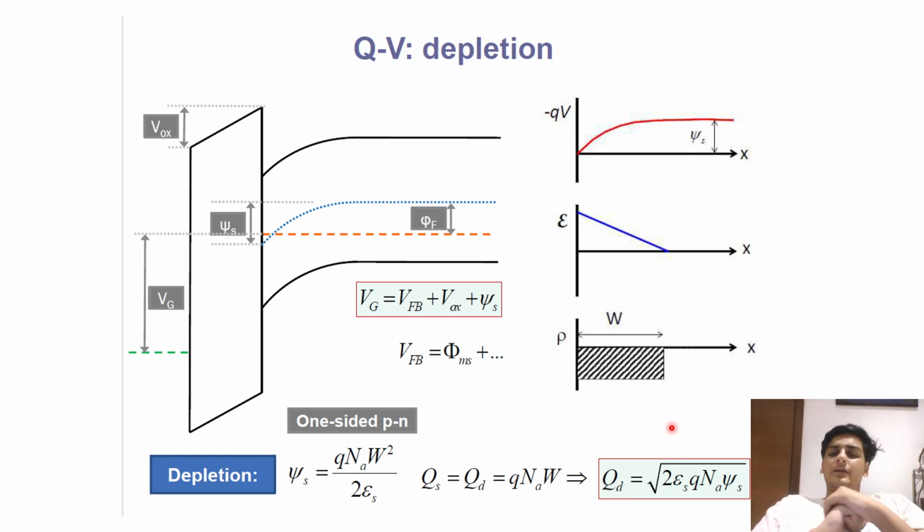And I want you to bring your attention now to our situation that we have here, where we have all the depletion across the P region. So does it not make sense to you that we can model this P region as being part of a one-sided PN junction where the N was extremely highly doped such that all the depletion happened across the P.